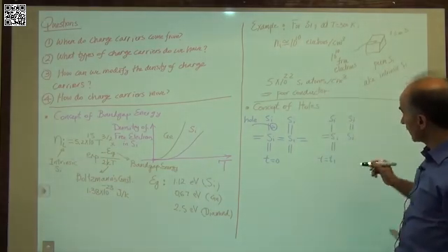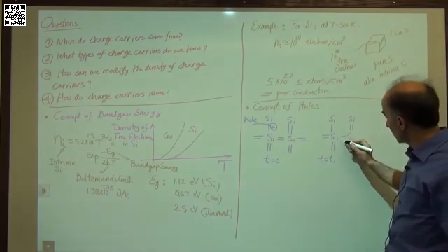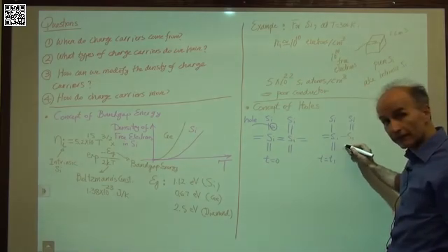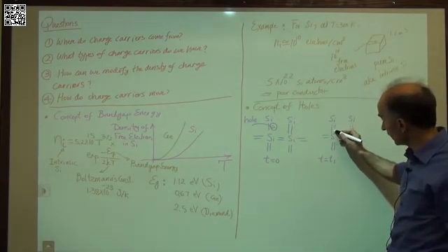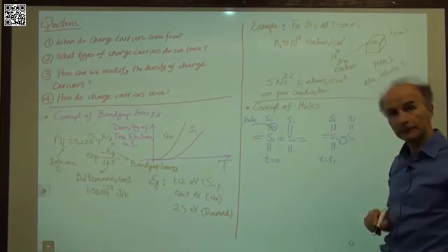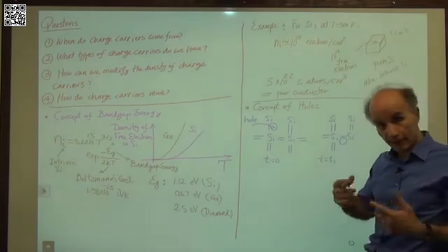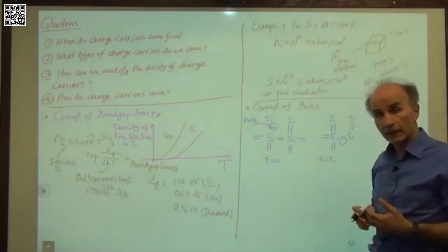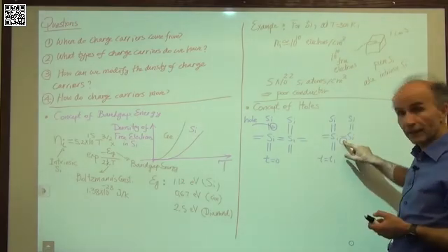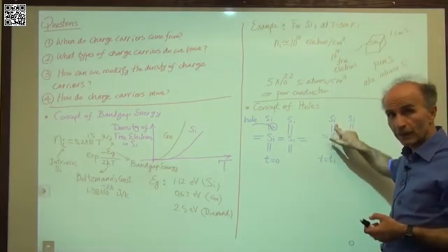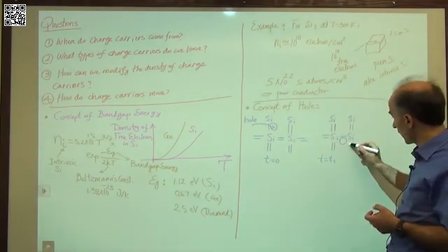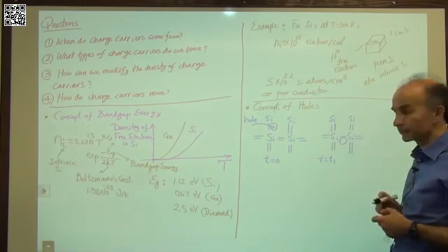What I see is that one electron has come out of this bond here and filled this hole here. So now the hole is here. Right? We know that every bond is capable of relinquishing an electron if there's enough thermal energy, and it just happens that this bond lost an electron, and this electron fell into this hole, completed this bond, and now we have a hole here.